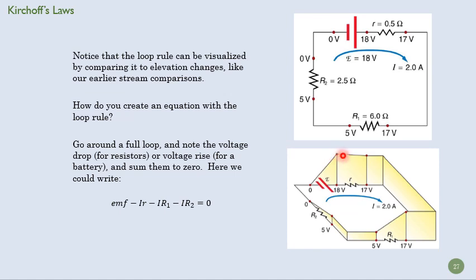And then as we go around the loop, how much voltage am I losing here? Well, I can use Ohm's law, V equals IR. And that's going to be the voltage drop there, and that becomes that term. It's going down because it's going through a resistor. The battery makes it go up. There's a positive number, then down through the resistor. I come down here, again, V equals IR. I want to know what that voltage drop is. IR. I is the same for all of these because it's a series circuit. And then finally, we do another IR there, and we set that equal to 0. So there can't be any overall change in the voltage.